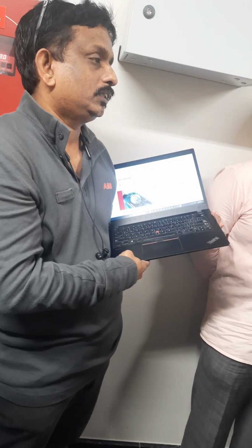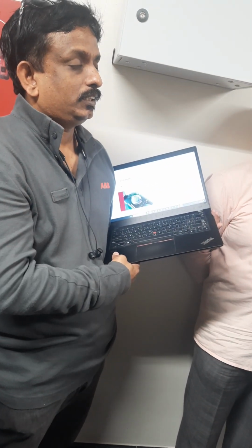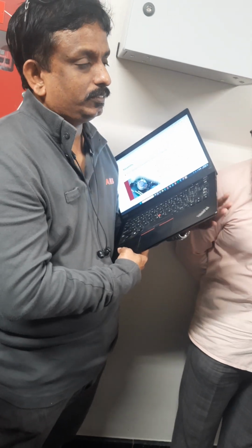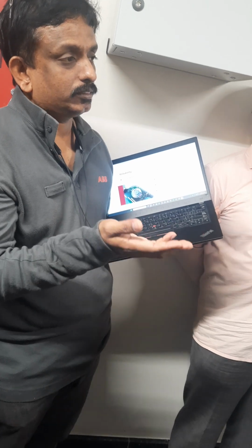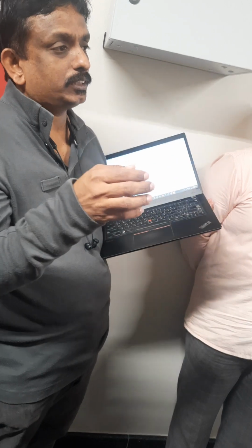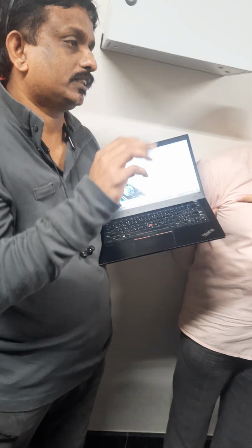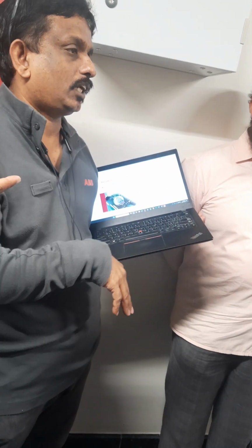We can check the status in this panel, right? Battery status? No, that's your side, not this side. In the VFD drive you have a battery. We have a battery in the drive, and that is for the control backup for the drive only. That battery will last for 15 minutes only. At that time the drive starts with the alarm, control supply low. After 15 minutes it will shut down the drive.